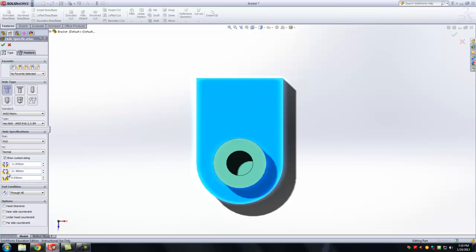So from here I can see that the diameter of my counter bore is 21.48, the depth of my counter bore is 6.85, and the diameter of the neck is 11. Okay, so that's why, remember, I said M10 is about 10 millimeters. So that's just an idea for you of sizing, but it has a different scope. Does that make sense? So now, if you want to customize those, you can definitely change those by typing in whatever you want, and so on.